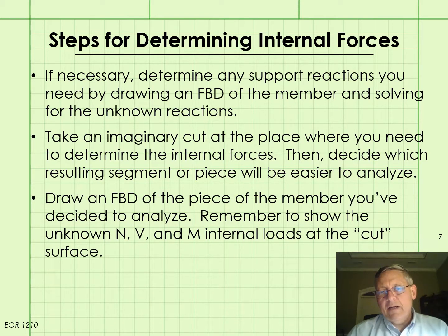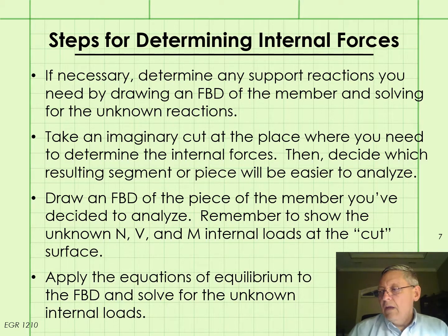Next, draw a free body diagram of the piece of the member that you're analyzing. And remember to show the unknown normal force, shear force, and bending moment, internal loads at the cut surface using the sign convention that we're following. And last, apply the equations of equilibrium to the free body diagram and solve for the unknown internal loads. Again, nothing different than anything we've been doing for the past several weeks.